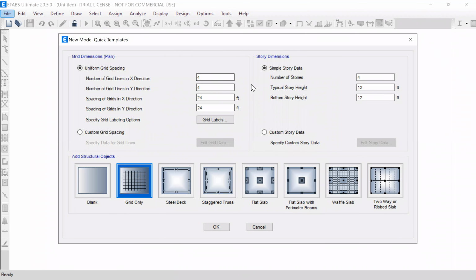First thing we want to do is create our grid space. In this case, beam width was defined as 15 in the tutorial problem. For number of stories, we will just do 1. Since we aren't doing an actual structure, we're doing a simply supported beam. You can change story height for your columns when you do the assignment problem. Make sure grid only is selected, click OK.